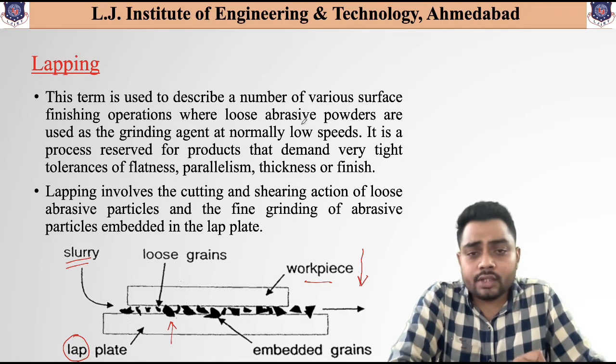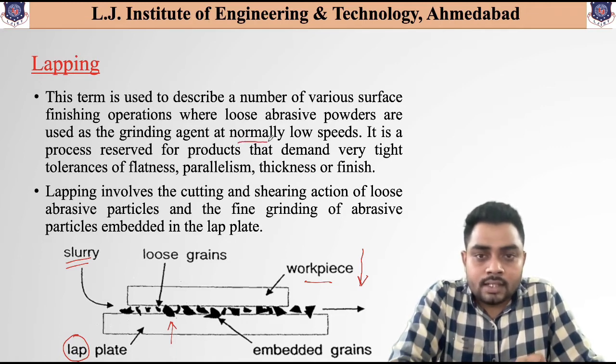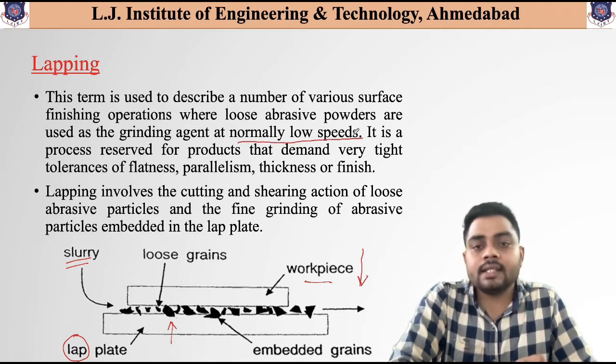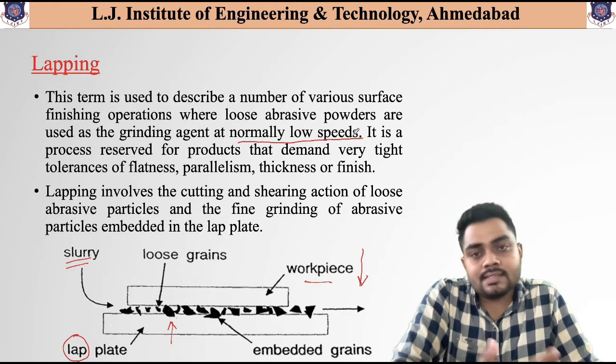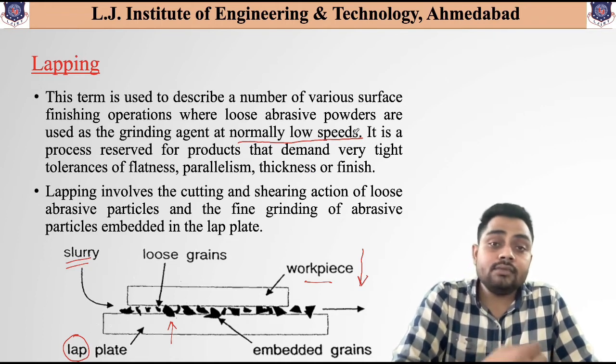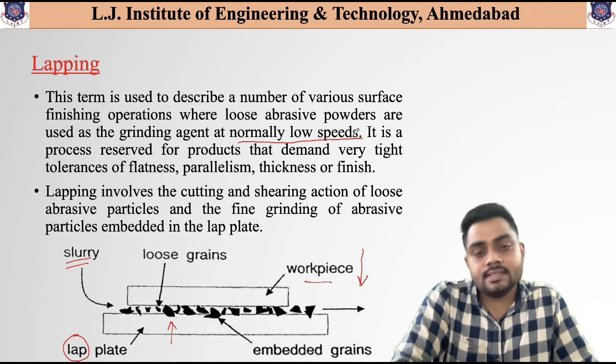And the mainly important thing that you need to look at is that this lapping process is performed at low speed, and it is mainly used to get tight tolerances, better parallelism, flatness and better finishing at the end of the surface.